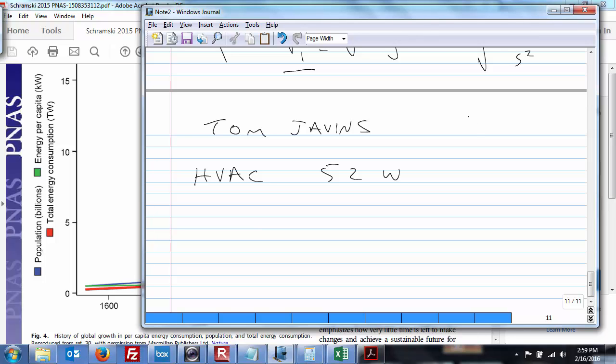Now, what he did, I've seen the house. He's got giant ductwork, like 12-inch tubes running through his house. Typically, you look at the ducting in a lot of houses, maybe 6, maybe 4-inch tubes. The deal is, as expected, in a 12-inch tube, the delta P, the change in pressure, is small.